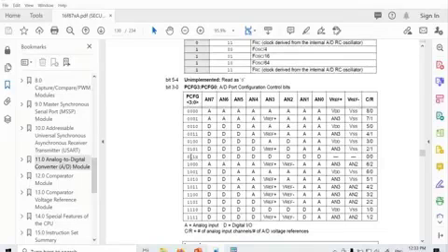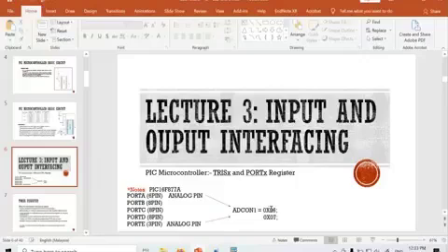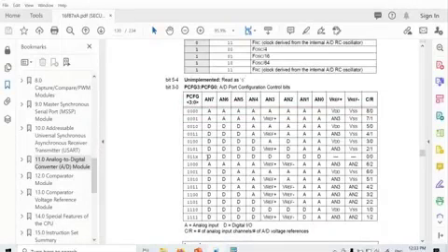So right now, as you can see, whenever we set ADCON1 to either 06 hexadecimal or 07 hexadecimal, this means that the pins AN0, AN1, AN2 up to AN7 will become digital. That's why you need to configure ADCON1. We want the ports that share a function with analog input to behave as digital I/O.